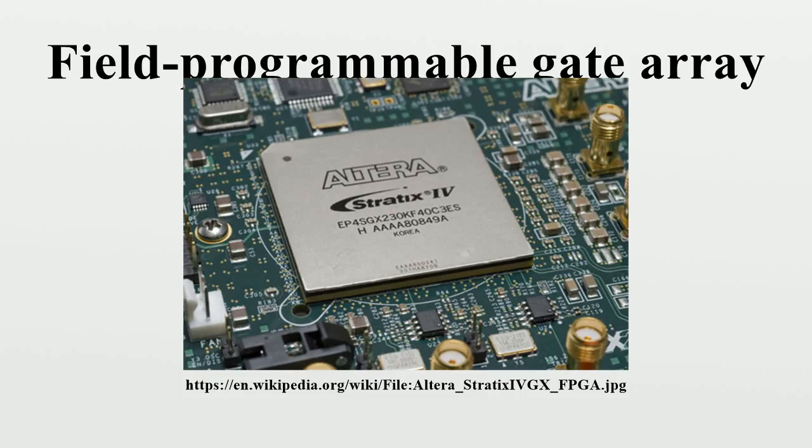FPGA comparisons. Historically, FPGAs have been slower, less energy efficient and generally achieved less functionality than their fixed ASIC counterparts. An older study had shown that designs implemented on FPGAs need on average 40 times as much area, draw 12 times as much dynamic power, and run at one-third the speed of corresponding ASIC implementations.